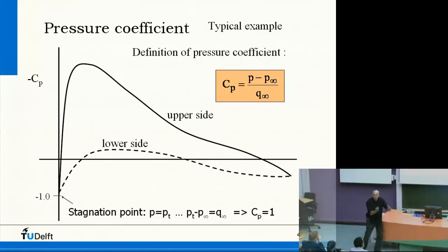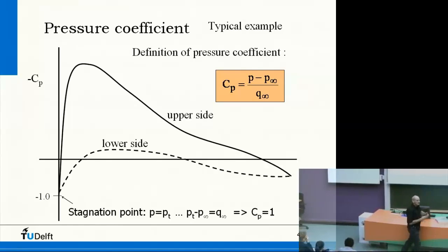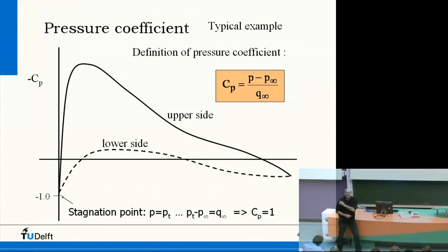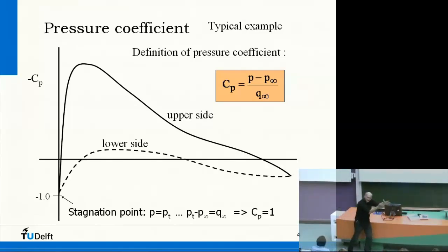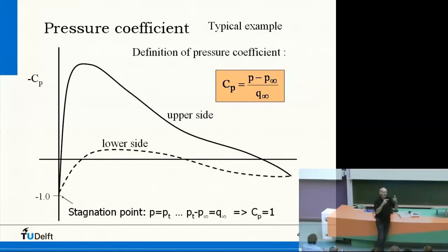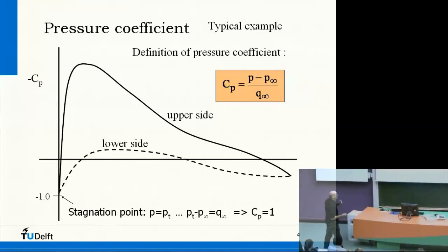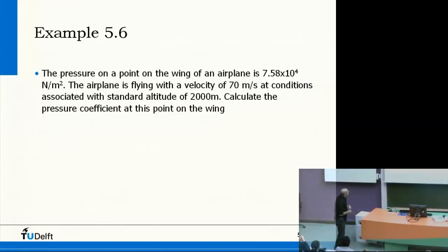And when we stop the flow, the same can be said from a reservoir, for instance, where the velocity is 0. If you remember the compressible piece about a wind tunnel, for instance, supersonic wind tunnel, then you have a big reservoir, you pump it up, high temperature, and then you release a valve, and then it's flowing to Mach 1 and further. And then in this reservoir, V is 0. So in this reservoir, we have the total temperature and the total pressure. Right? Okay. I will come to that later, maybe. Okay.